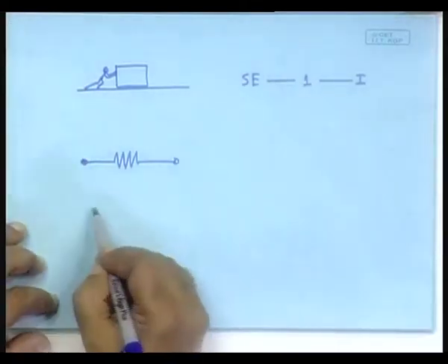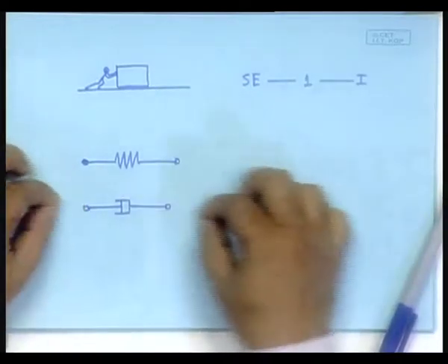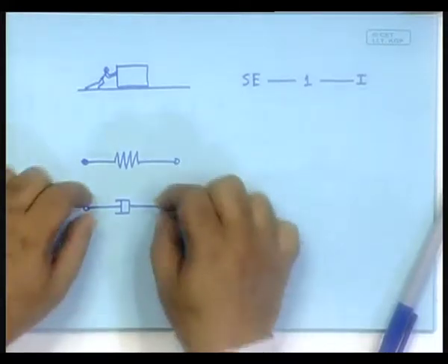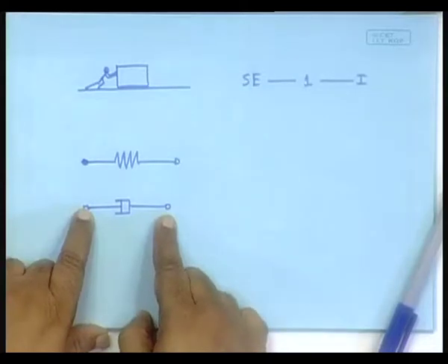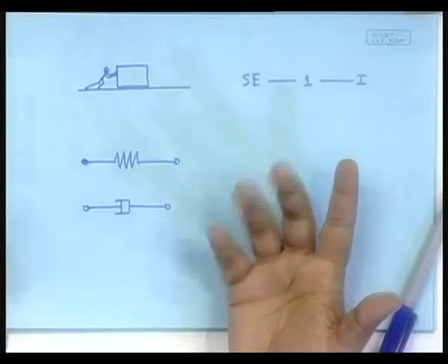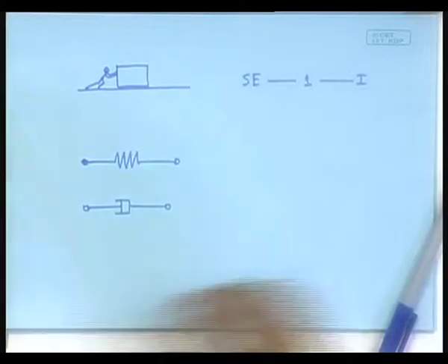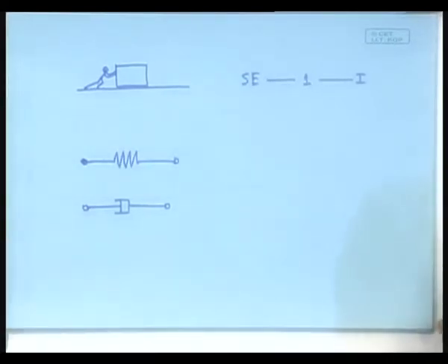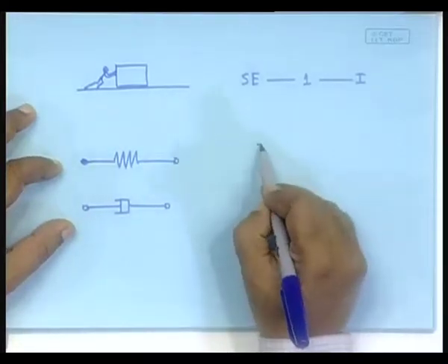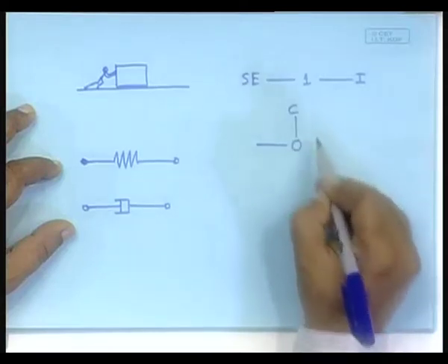Same is true for a resistive element. Just move them, the 2 ends must feel the same force, right. So, if these 2 sides feel the same force, then whatever is at the 2 sides shares the same effort, which means they are connected by a 0 junction. So, in that case we will represent this as a bond, 0 junction, to a C element, to another.